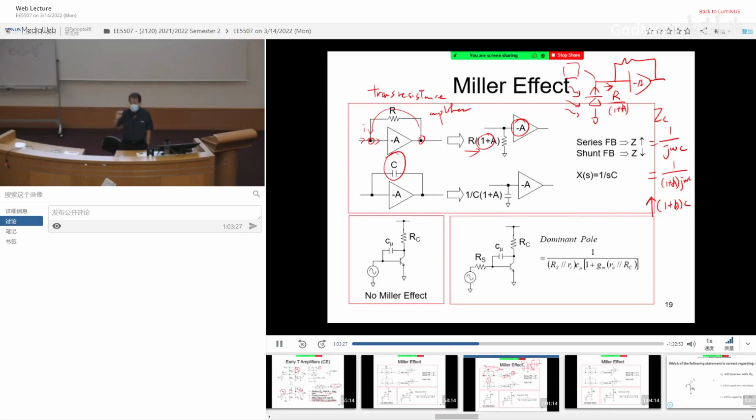tells you that you can get a much larger capacitance with just the same capacitor. Right? So it gives you the moral story. Not everything is bad. Even the worst thing might come in handy sometimes. Okay? So Miller effect, people do use it to boost the capacitance, especially in filter design. If you want a large capacitor, no way to go. I want to boost the capacitance by 100 times. Miller effect. You just have to design an amplifier with 100 times gain.